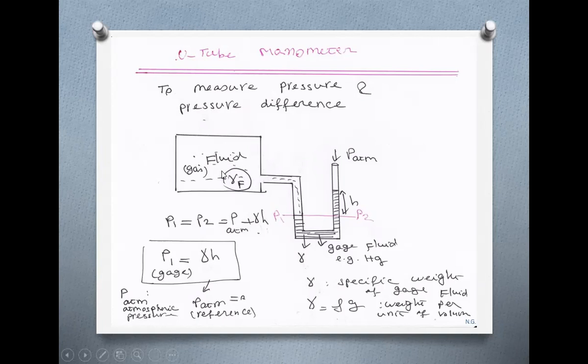So you say, okay, pressure inside this container, let's say here, is the same as you go horizontal and pressure doesn't change, and you go down and pressure doesn't change. And you are here, then you go horizontal from point 1 to point 2. And because you go horizontal, pressure doesn't change, because points which are in the same level in the fluid experience the same pressure. So you say, okay, P1 is equal to P2, right?